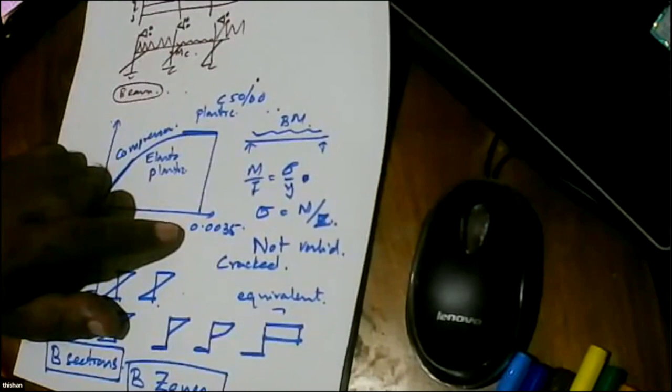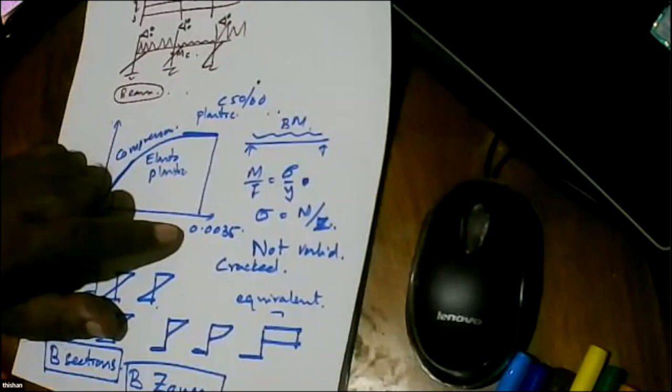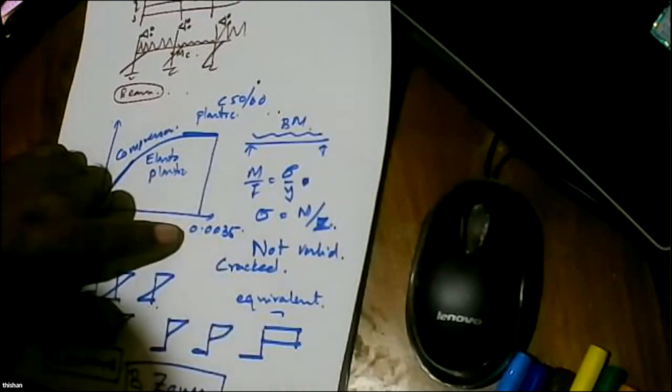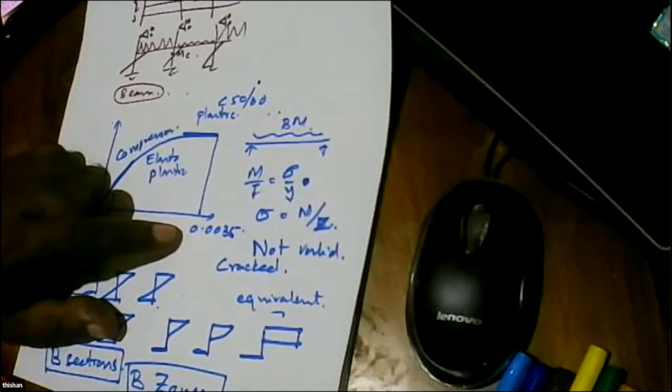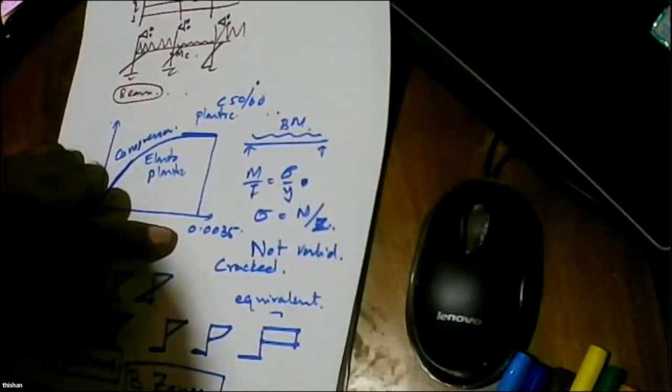But theory is theory. But people did not know about this theory called D zone. So they said, okay, strut and tie, because the test results do not comply with the beam theory. They give different results. So they came up with strut and tie, which gives a better result. But they were not explicitly telling us. They said, okay, if it's a pile cap, you must use the strut and tie method. If it's a corbel, you must use the strut and tie method. So they were giving a solution, but not explaining the problem adequately.